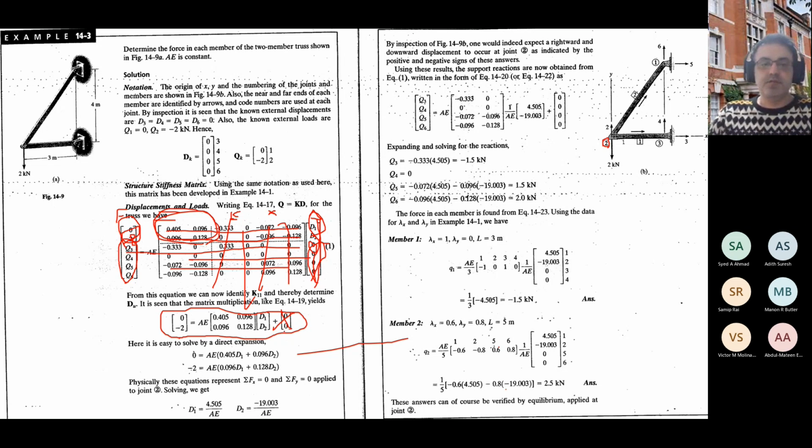And if you try to invert this remaining stiffness matrix, the matrix is reversible. Otherwise, if you try to invert the bigger 6 by 6 matrix, it's not reversible, and you will come up with a determinant equal to 0 or negative, and it means that it doesn't have any support, and it should be like that.